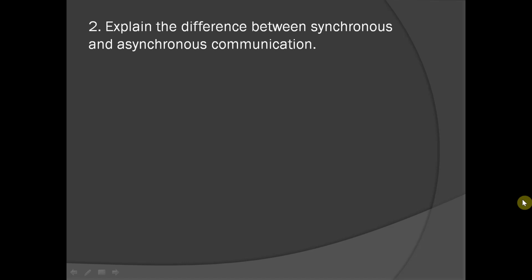In asynchronous communication, the two clock domains have different frequencies. Clock domain 1 is working with some frequency, and clock domain 2 with another frequency. Here, if the transmitter wants to send some information, there will be data corruption if there is no synchronization between the two domains.